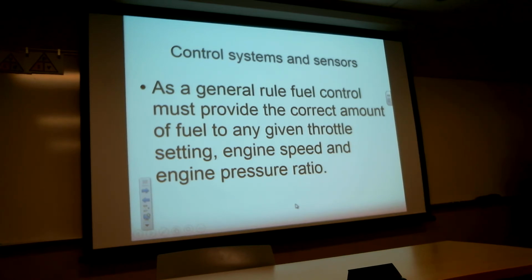So if you have an aircraft that does nothing but fly around carrying cargo, cargo is a big, heavy object, and so you need a lot of thrust to move it. But when you have passengers on board, you don't need as much thrust. So you don't want to burn as much fuel at that 100% throttle lever angle. So you reduce the thrust rating on the FADEC. You put this plug on there. Has to be a logbook entry made. You flip the data plate over to indicate the new thrust rating, and you're good to go.